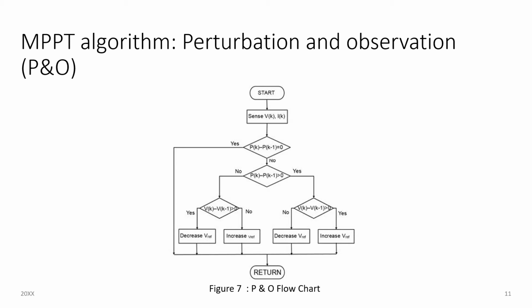Engineers developing solar inverters implement MPPT algorithms to maximize the power generated by PV systems. The algorithms control the voltage to ensure that the system operates at the maximum power point, or peak voltage, on the power voltage curve.